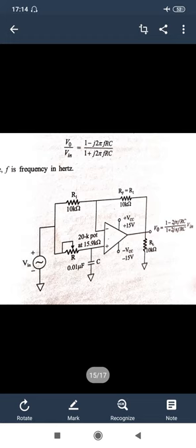Next we talk about all pass filters. All pass filters are circuits that pass all frequencies, so they are also called delay equalizers or phase correctors. It is a filter that passes all frequency components of the input signal without attenuation. Its function is to change the phase of the signal without affecting its amplitude, so it is also called a phase shifter.